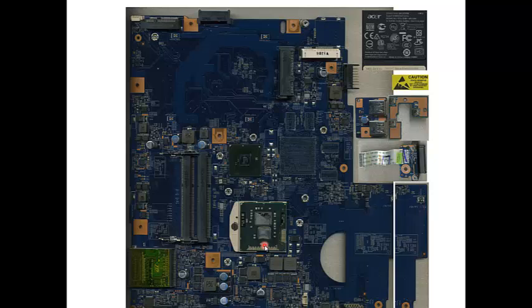Okay, so when you turn on the laptop and the laptop is not giving the display, then you have to check all the voltages across each coil. Like you see in this, there are different coils, here is a coil, here is a coil, here is a coil, here is a coil. These are the different coils, and each coil gives a different voltage. Like here you will get 3.3, here you will get 5 volt, then here you will get 1.05 volt, here you will get 1.5 volt, 1.8 volt, like that.